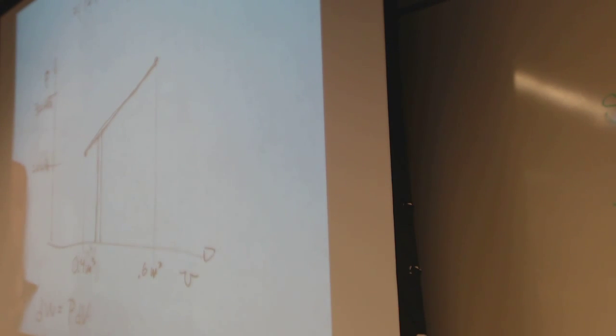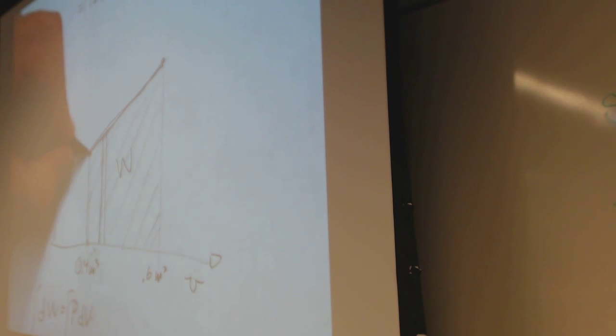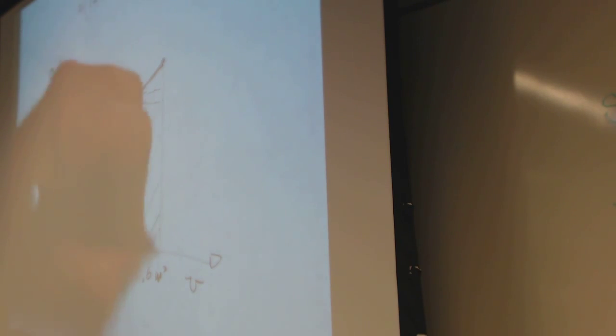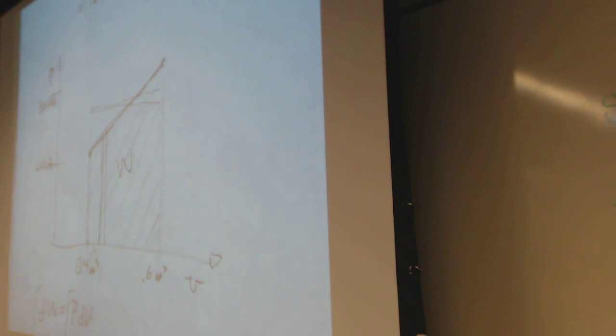And if we add these all up, what it's telling me is that that adds up all this area under here. It had to use this much pressure times that much distance. This is the work done. So do we need to make a calculus formula to solve this problem? It looks a lot like, well, the same as if we took a rectangle that has a height of the midpoint there, right? Just geometrically looking at it.